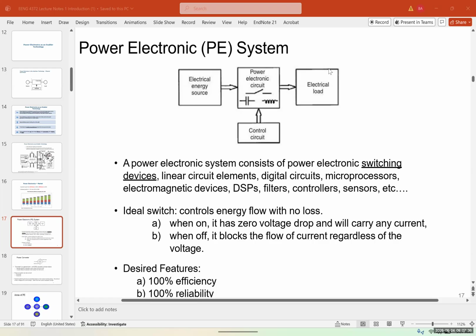So to have a pure sine, and I'll explain this, it requires multiple steps. Instead of one switch, you may need 10, 20 switches, and it gets much larger, much more sophisticated. That's the reason a house inverter that is grid tied is like $2,000, $3,000, but the same inverter with the same power is going to be like $100. So if you see a $100, $200 one that is 2K on Amazon, they're usually very cheap ones made for cars.